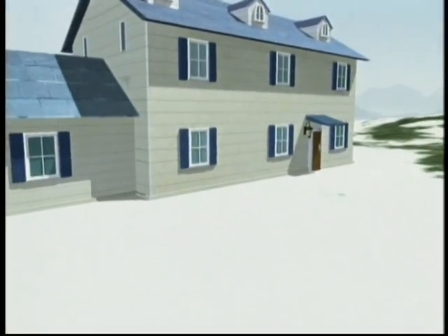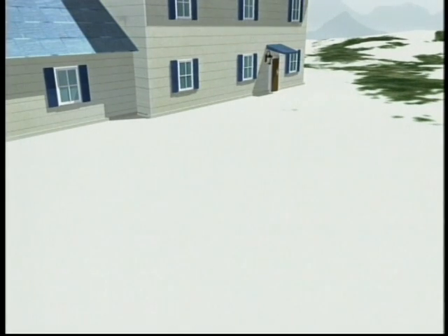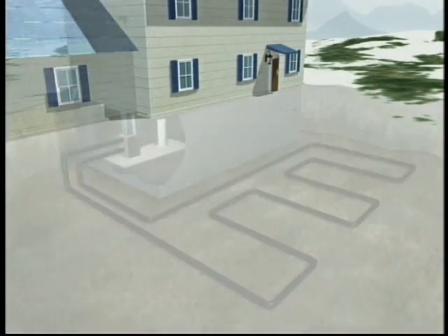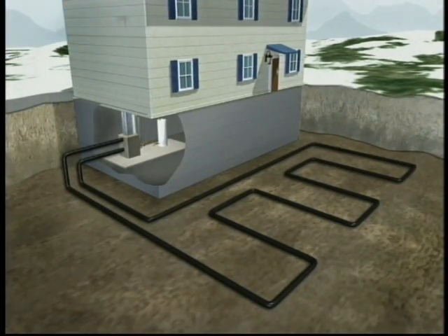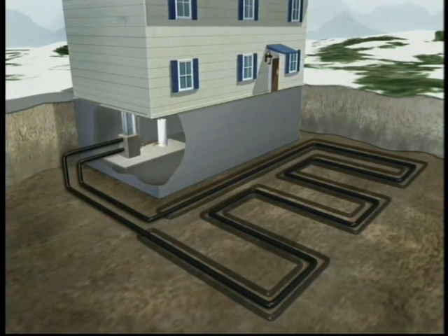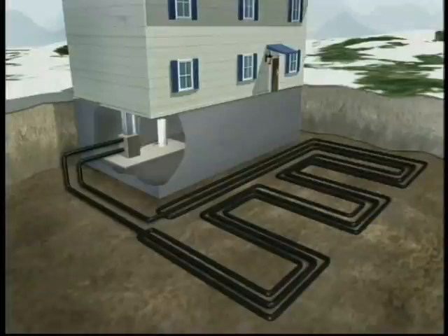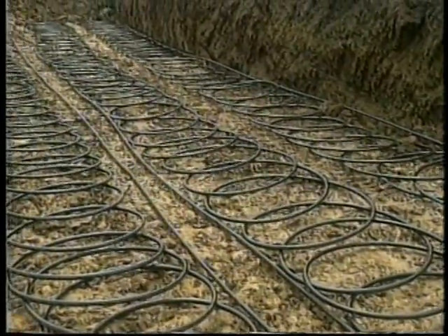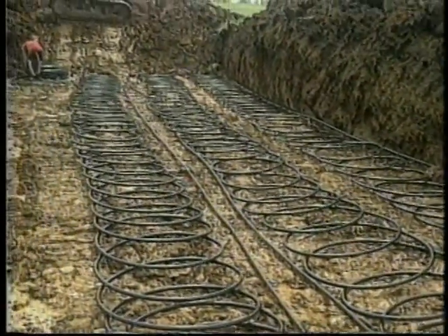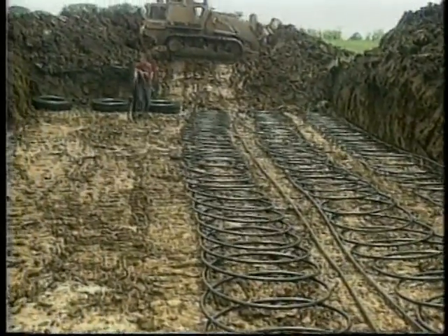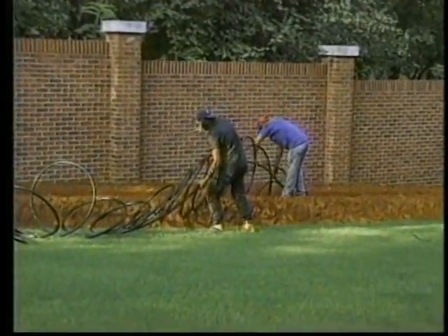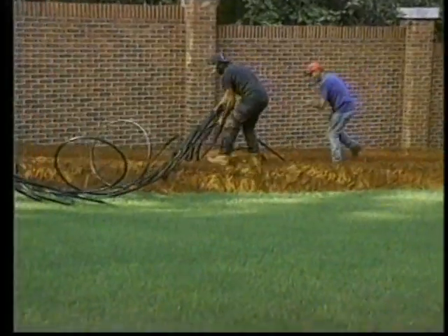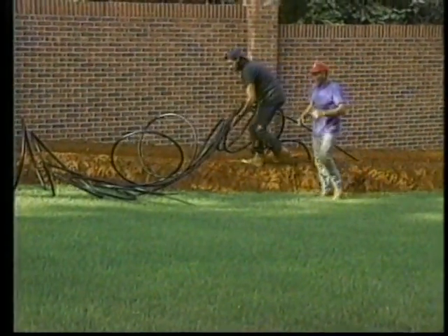In some installations, the pipes of a closed-loop system can be placed in a horizontal trench dug below the frost line. The number of pipes in each trench and the number of trenches needed will vary depending on the size of the GEOexchange system being installed and the type of soil found in the area. To minimize trenching, slinky coils, spring-like coils of polyethylene pipe, can often be used to increase the pipe surface area and thus the heat exchange per foot of trench.